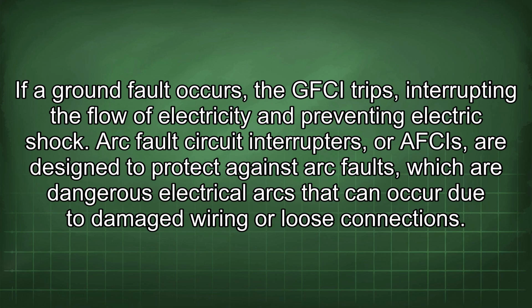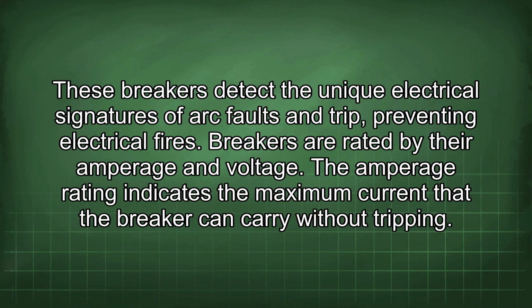Arc fault circuit interrupters, or AFCIs, are designed to protect against arc faults, which are dangerous electrical arcs that can occur due to damaged wiring or loose connections. These breakers detect the unique electrical signatures of arc faults and trip, preventing electrical fires.